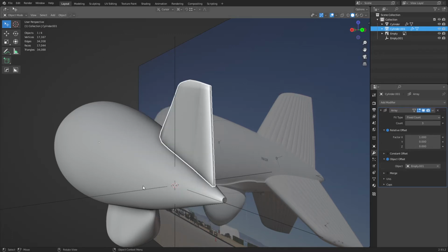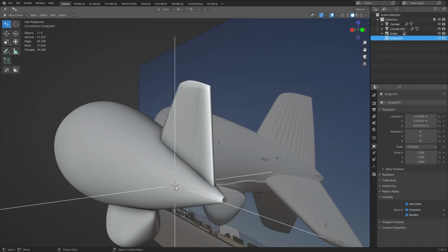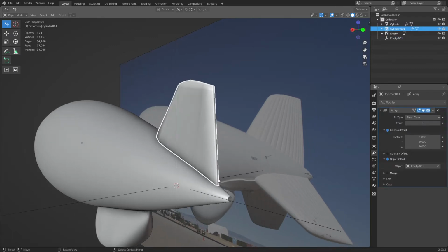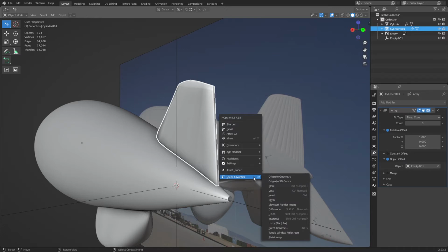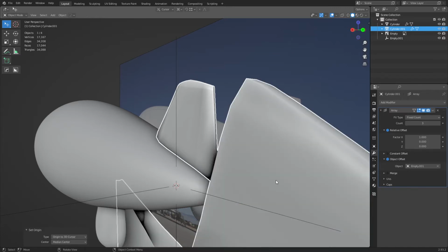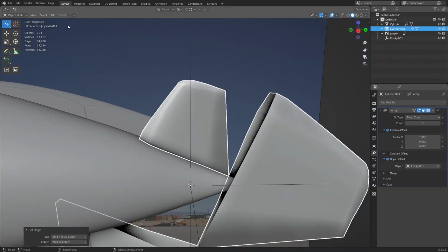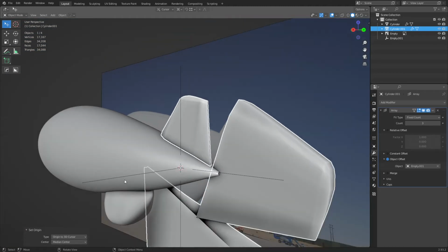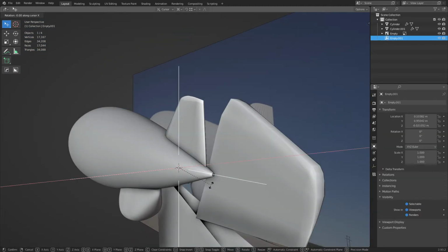For this to work, this empty has to have its origin point and this origin point for this object meet at the same position. And so what we're going to have to do now is just origin to the 3D cursor. All right, object, set origin, 3D cursor. Don't do relative offset, just object. And we're probably going to have to rotate this in one way or another.